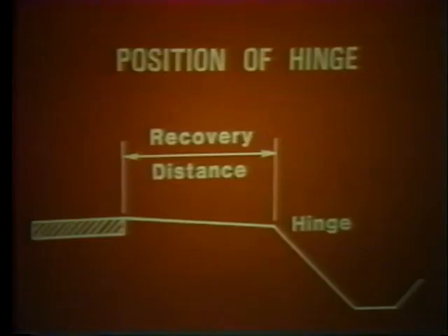The distance between the travel lane edge of a road and the point where the slope begins greatly influences safety. A steep slope located right beside the travel lane is not as safe as the same slope located 20 feet from the roadway edge. The greater distance gives drivers space to regain steering control before reaching the slope.